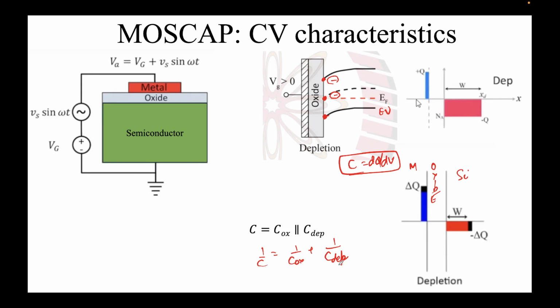We have talked about depletion now. Let's go to inversion. We have flat band. We'll apply some bias, this time a highly positive bias. We are in depletion, right? And now I apply the bias even further. So now we have entered the inversion. You can see that the bulk EF is closer to EV on P type. However, at the surface, EF is closer to EC. This is Ei, this is EC. This is the surface I'm talking about. So the material has been inverted, and this is how the charge profile looks. This is your depletion, the red, and the green that you see is your inversion charge.